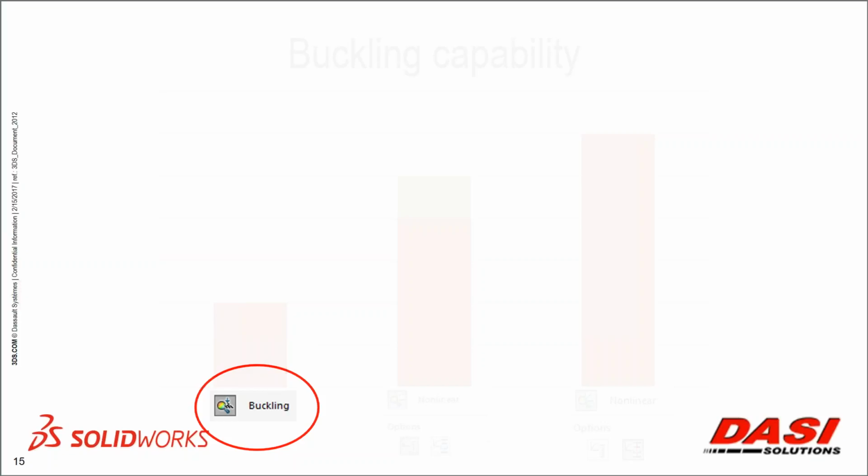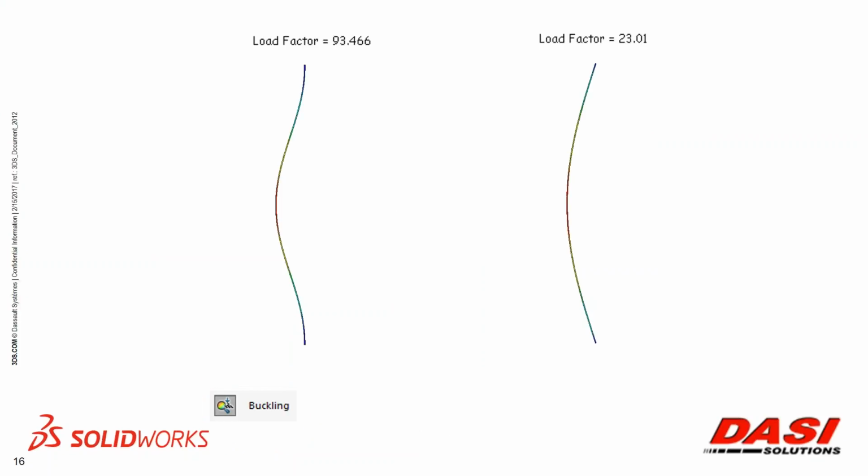So if I were to run a linear buckling scenario on, let's say, just a simple beam, or in this case a meter stick, just to make it a little bit more intuitive, less abstract, we might expect to see one of two buckling shapes. One buckling shape that we might see, depending on how thick the meter stick is and exactly how you're pushing down on it, if you're using the palm of your hand, which is really soft, or if you're using something rigid, which might actually exert a little bit of a moment, you might get two very different buckling patterns.